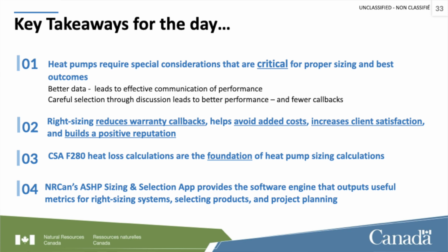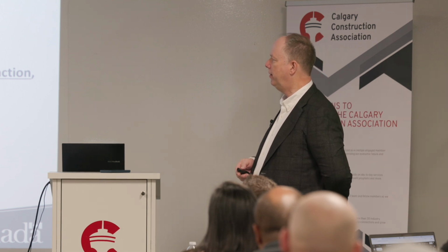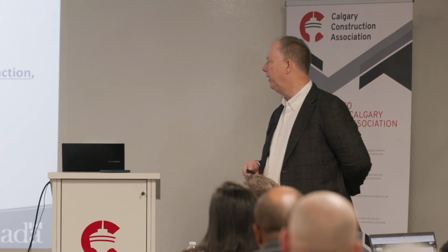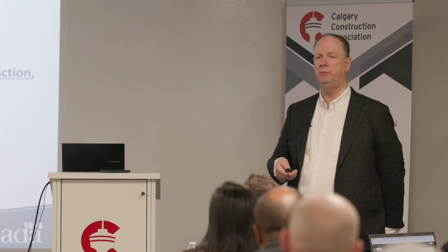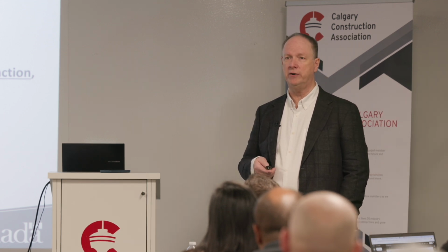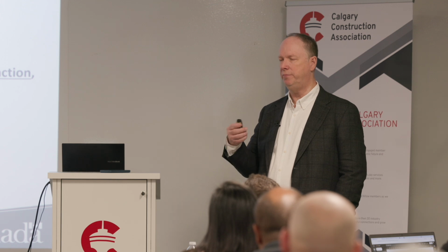The F280 is the foundation. If we're doing heat pumps, F280 is absolutely where you want to start, as a minimum. And as a minimum, we want to do that whole house calculation. If you really want to get into it, the whole home design is a great way to go. I do recommend builders try this once or twice. It can actually have an effect on how you design homes. We also figured out that NRCan's sizing tool provides a software engine. It provides useful outputs. It's a great conversation starter, and we can help customers and builders meet their goals with it.